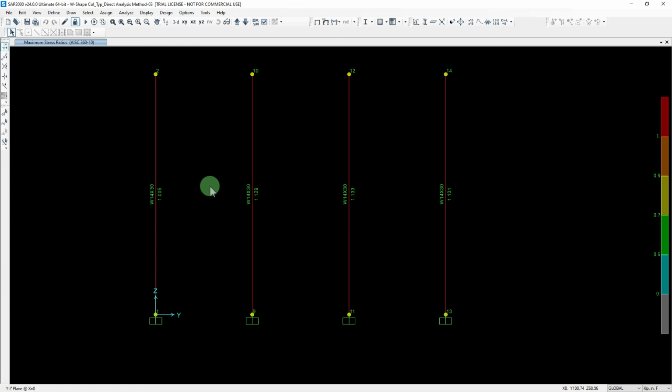And you can even say at 2 elements they converge. So 2 elements would be the absolute minimum. 4 elements would probably be more than enough, but it would be what a conservative engineer, depending on the sensitivity of the structure, probably would want to accept. Having more than that doesn't really affect anything other than analysis time, but you can get a little bit more detailed information.